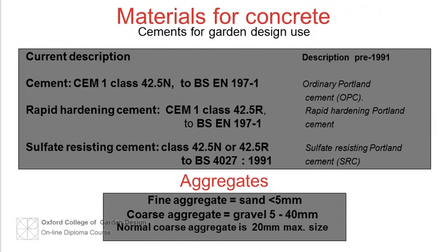Cement is basically limestone mixed with clay and heated in kilns to a very high temperature and then ground to a fine powder. The manufacture of cement consumes a great deal of energy. There are 7 main types of cement and a number of strength classes for each, making a total of over 30 different specifications.